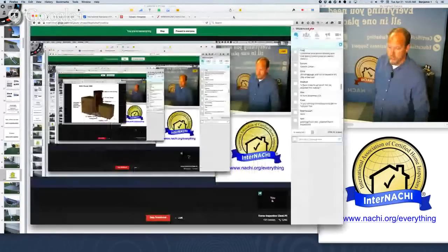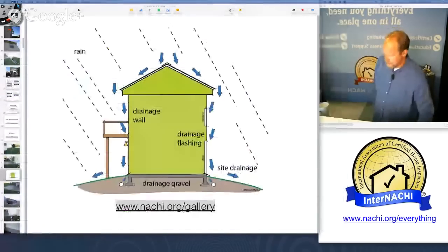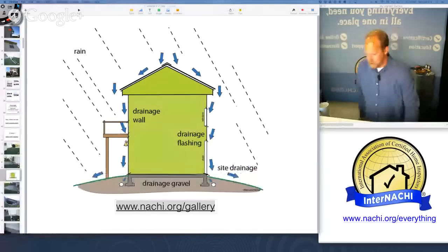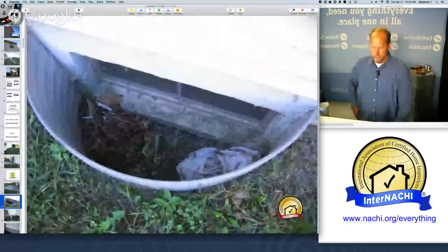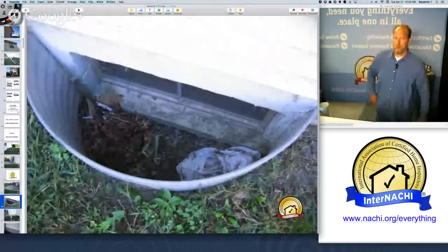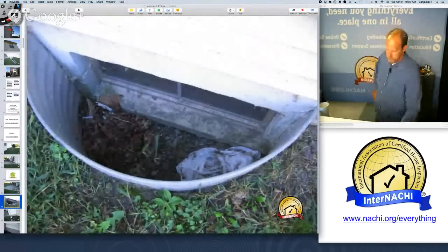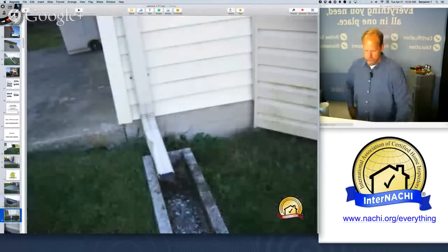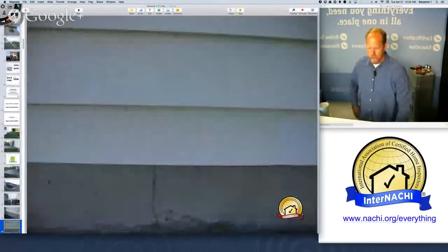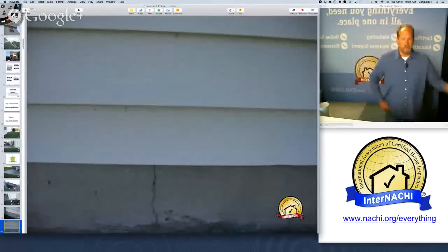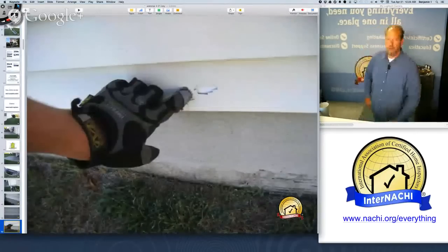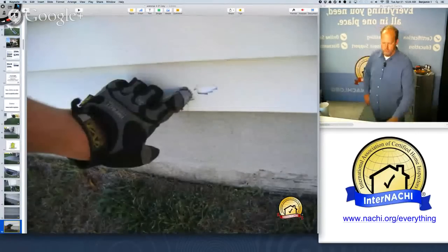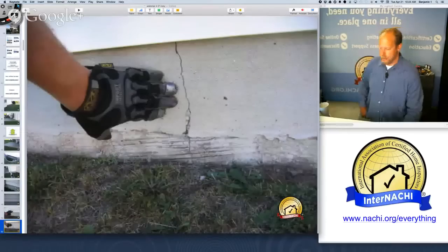Around the foundation, as an example. All right, let's get back to the exterior. So think about water, particularly in this house. Window wells, this house has a basement. This is a northern climate area, so it has a basement, downspouts, some minor cracking at the nice cement parging around the foundation, cracking at the mortar joints. Looks like a weed whacker or a lawnmower cracked the vinyl siding.